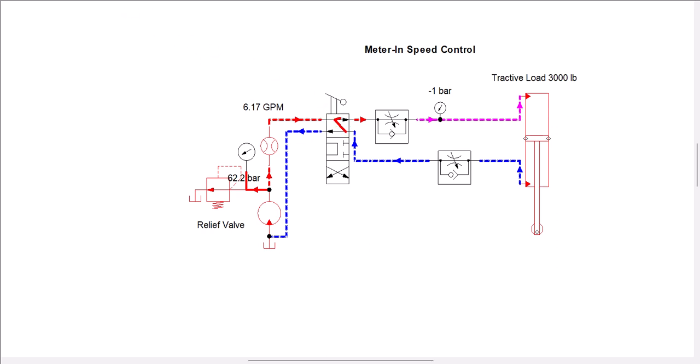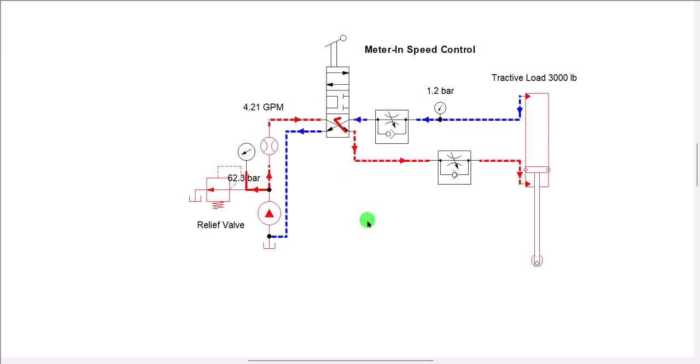Okay, so I'll continue with normal speed. You see continuously this one suffers a low pressure, and this fluid is easily traveling back to the tank, which causes the entire downstream line to be at 0 pressure. When we do the retraction, the piston is pushed up by the fluid under the piston.